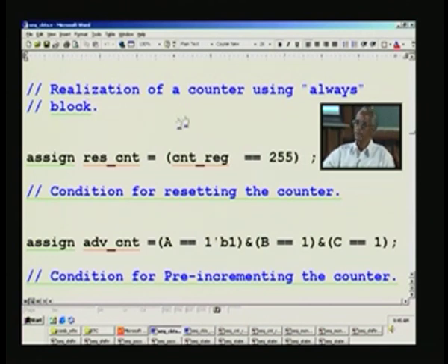And if it is ASIC, I have tried 0.13 micron technology also. I have done it for MPEG video compression, say DCTQ etc., which we will be showing later on in the design applications, and in that I had achieved around 270 megahertz in 0.13 micron technology. You can jack it up to 300 megahertz. Only thing, synthesis will take a long time in ASIC.